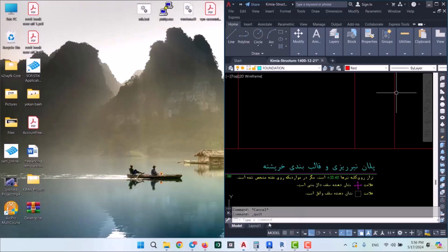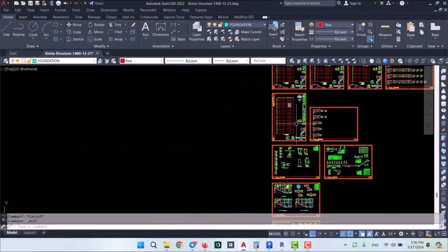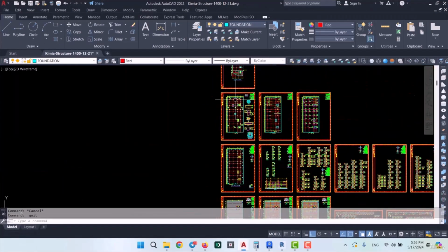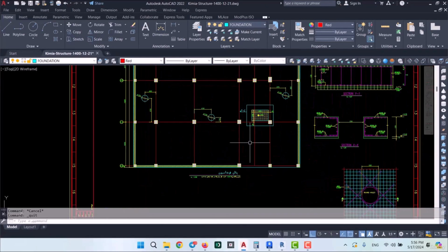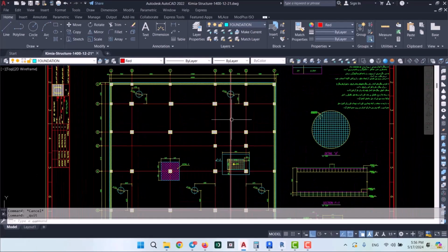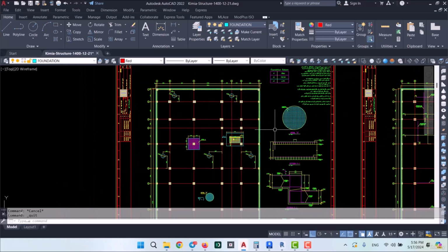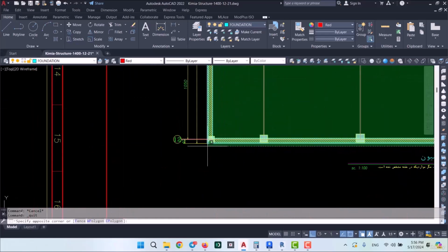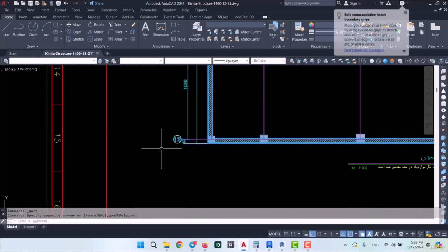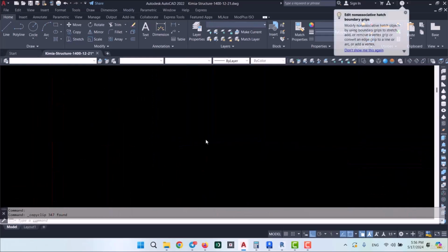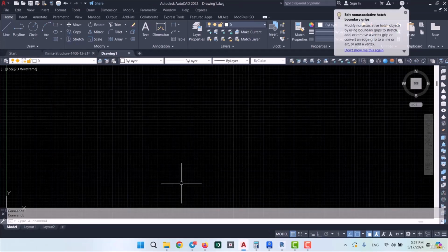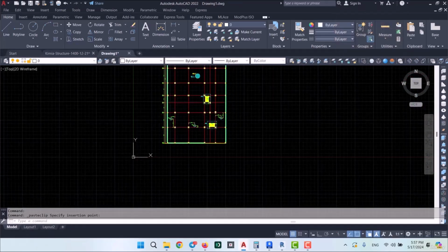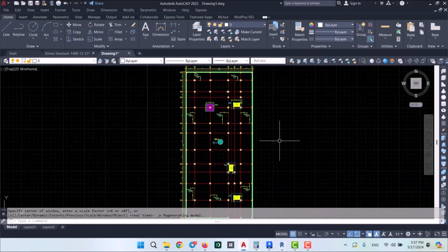You see, I've already opened the structural plan over here, and now I'm going to go up a bit. And this right here is where we have the foundation plan. So in order to draw the axis, we're going to have to import this plan into Revit. The first thing I'm going to do is copy this plan, without its titles, hit Ctrl+C, then open a new file, and then press Ctrl+V. We're going to also place it here for now, and we're going to reposition it later.